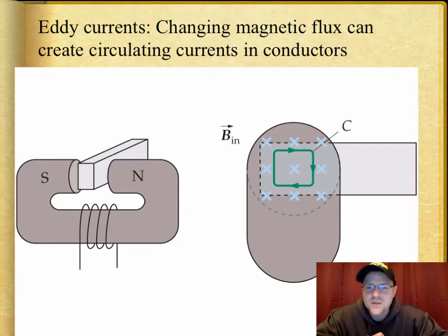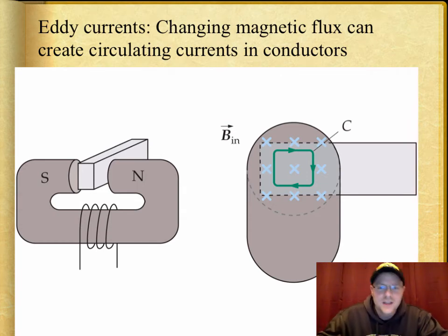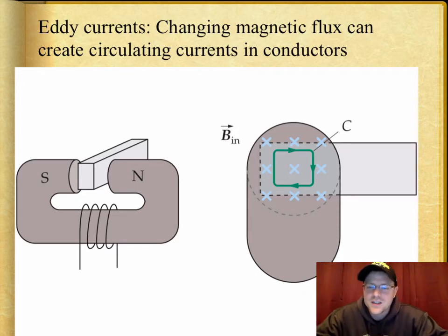To resist the change of flux, it's going to create a magnetic drag. And in this case, it's going to try and keep that conductor in the magnetic field. If it was outside and you try to push it in, the drag force would fight that change in flux and stop the conductor from moving towards the middle. And that's exactly what we just showed you in the demo.